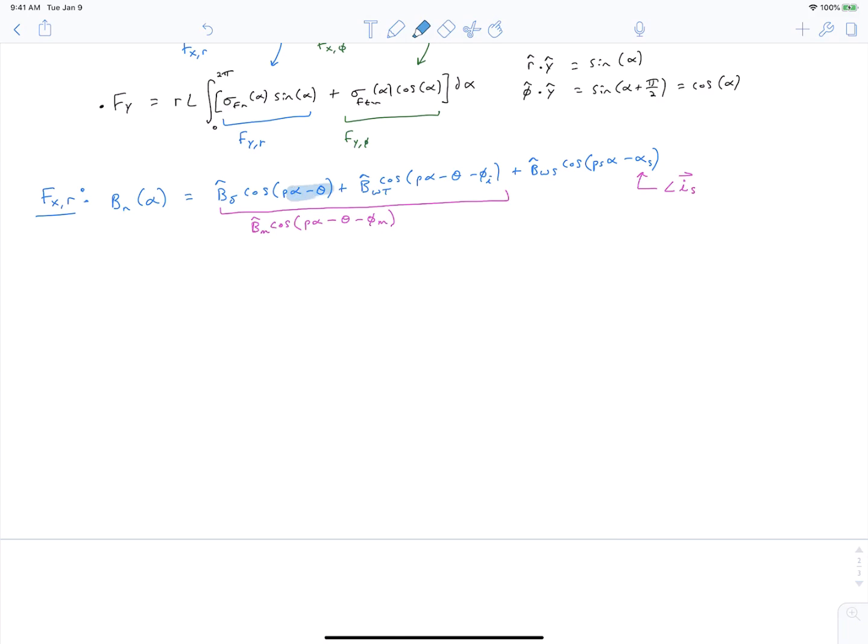You see that these two fields are very similar. They just differ by the angle of the suspension, or the torque current space vector, which is phi. And so we'll lump this into a single field for ease of solving these equations. And we can always decompose this back out to these two terms if needed.